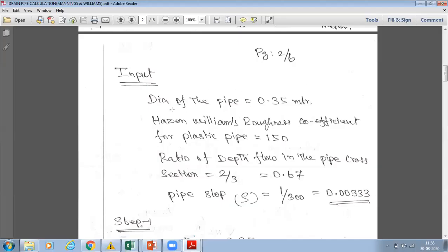So now we are getting the flow rate for the pipe size only. I have considered a 0.35 m, 350 mm pipe size only, for this calculation. You can do it for 75 mm to larger sizes. Whatever sizes you are going to use for your project, you have to put those first. Once you have arrived at the formula in Excel, all the calculations are easy for you.